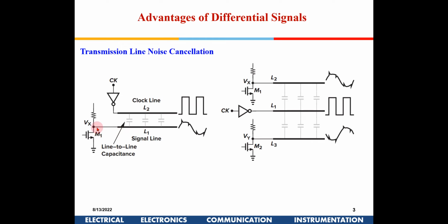For example, you have one chip and output from one particular stage, and you have a wire which is sent to another part of the chip where you have some other component, or it could be outside the chip or within the chip. So obviously in the routing you might find there are other wires also running. As an example, there is a clock line running parallel to this for a certain distance, and in clock lines there will always be steep changes, 0 to 1 and 1 to 0. Although there are no capacitors connected between these two lines, there will be some stray capacitances, because after all this is metal with an insulator in between. So it is bound to happen that certain transitions get coupled into the analog signal. So this is all noise coupling.